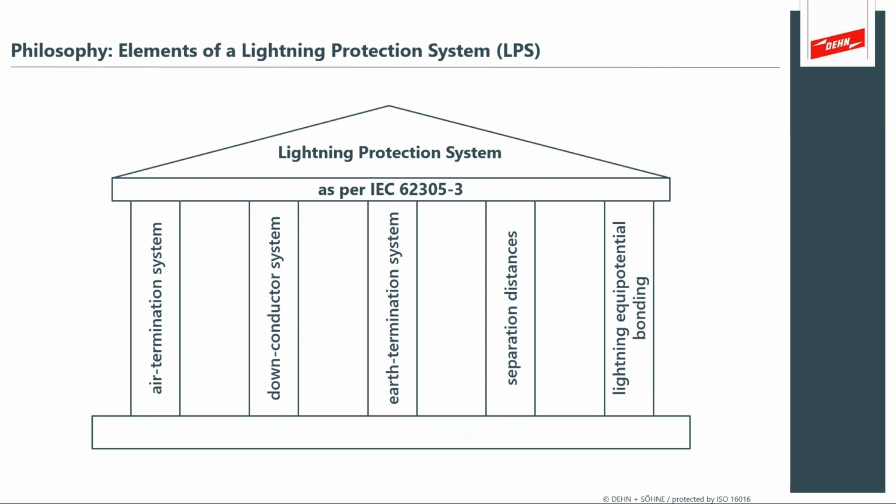But we need to pay attention, Simon, while we're doing this, three major functions, we also need to pay attention to how we do it, how we space it away from the other critical electrical apparatus, your chillers on the roof, your other electrical systems that run through the walls of the structure. And then the fundamental issue of bonding, lightning equipotential bonding.